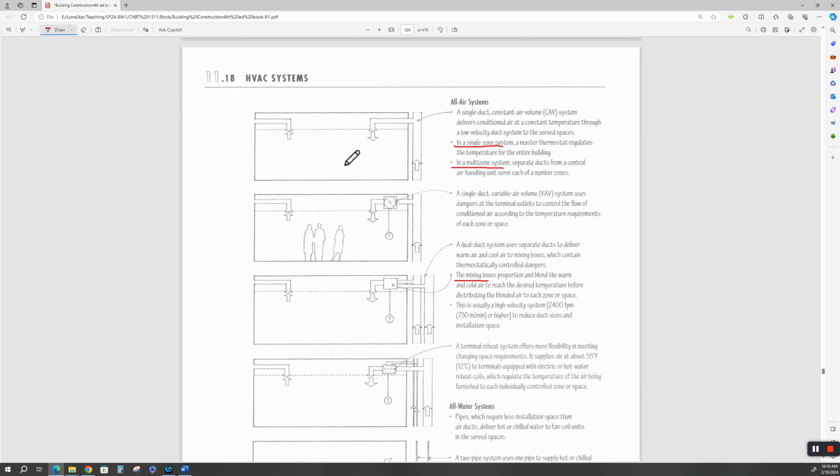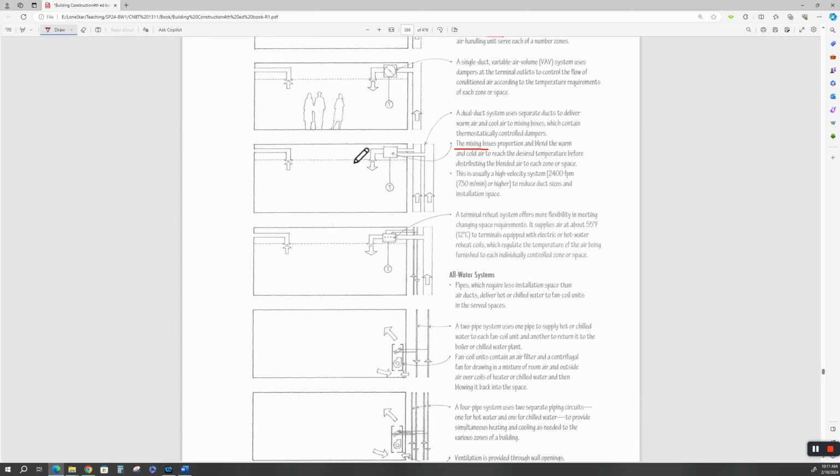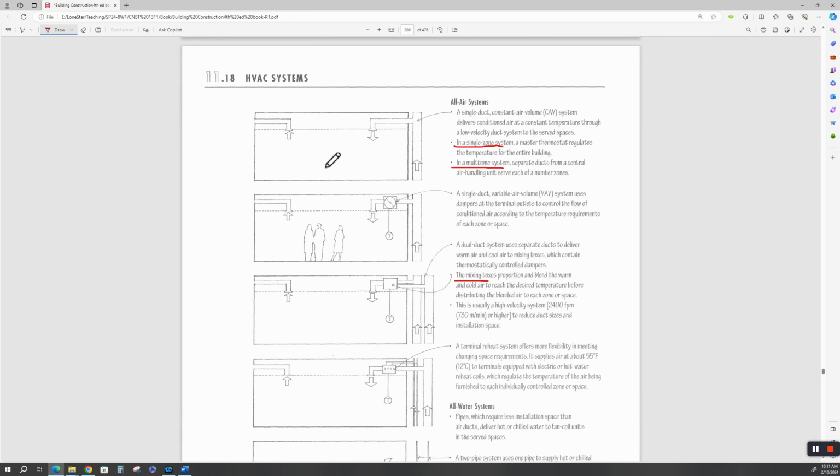Your residences are mostly a single zone system, although there are some residences that have a split zone system, so they'll have two separate air conditioning systems for the house. So you'll see two compressors sitting outside the house, or three. Now Daikin has come up with a split zone DX system that uses a single compressor, and they use splitter boxes throughout the residence. And that system is also a multi-zone system.